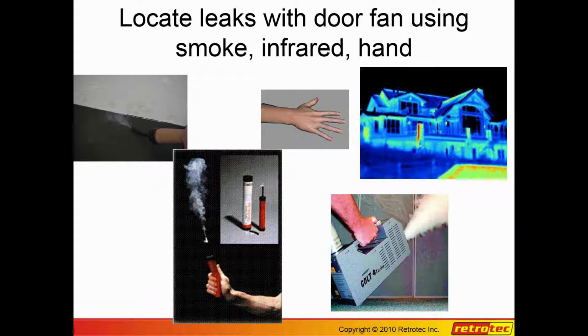But one great thing about this kind of burn tester or smoke puffer is that it will detect pinhole leaks. You need to get really close to the item and put a tiny amount of smoke in there, like a cubic centimeter, a 1/4 by 1/4 inch blob, about the size of a pencil eraser. That's all the smoke you need to test an individual component. And if that is leaking, if you can see this picture here, the smoke will snake into that hole and identify it.